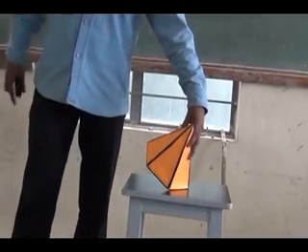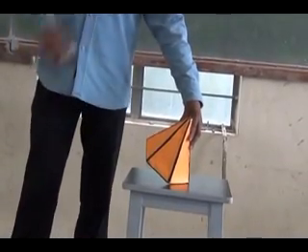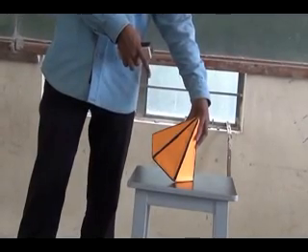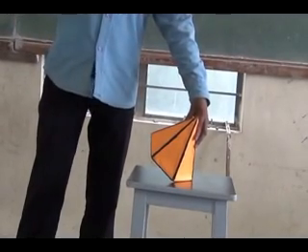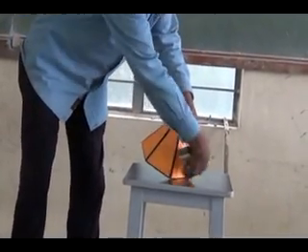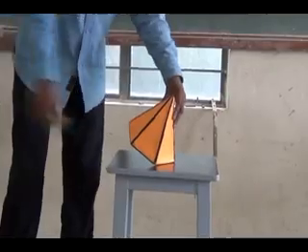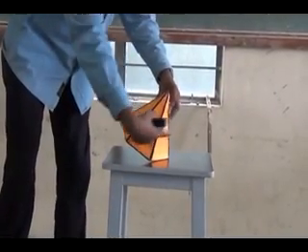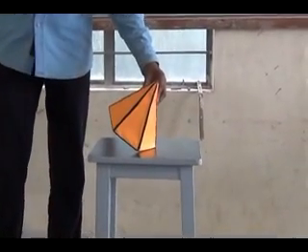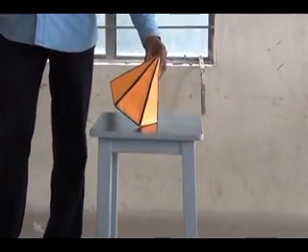But what is the other condition given? A triangular slant face. This hexagonal pyramid has 6 triangular slant faces. So a triangular slant face containing the resting base edge. This is my resting base edge; along that I will have a triangular slant face. That triangular slant face orientation is given.